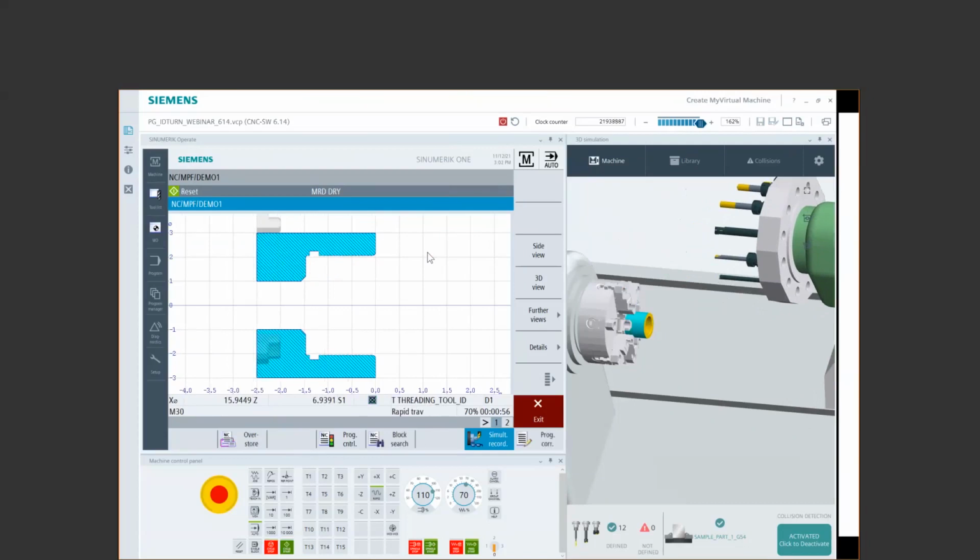There we have it. We have a quick little part. So that's really a kind of a good start. I mean, there's not a lot of differences OD to ID. Really the big thing is just paying a little more attention to where the tool is, because you have a little more crash potential, right? So add those extra retracts from a safety perspective. Maybe get in the habit of pre-positioning the tool in before you go right into an operation.